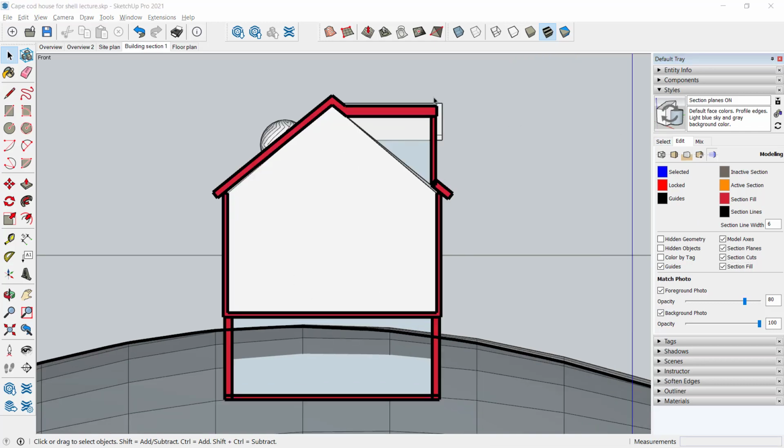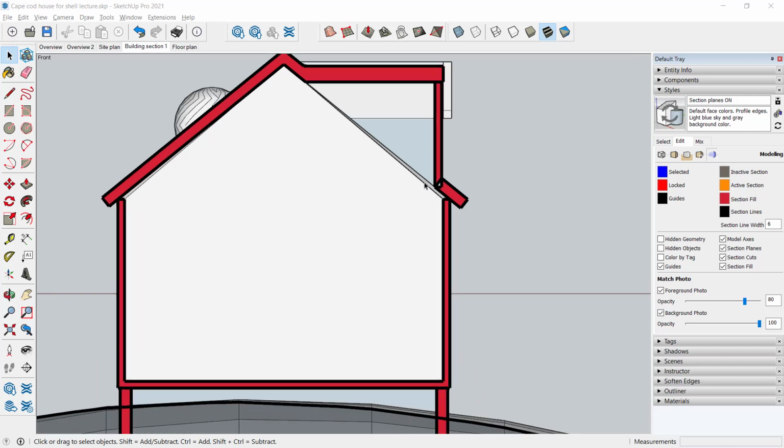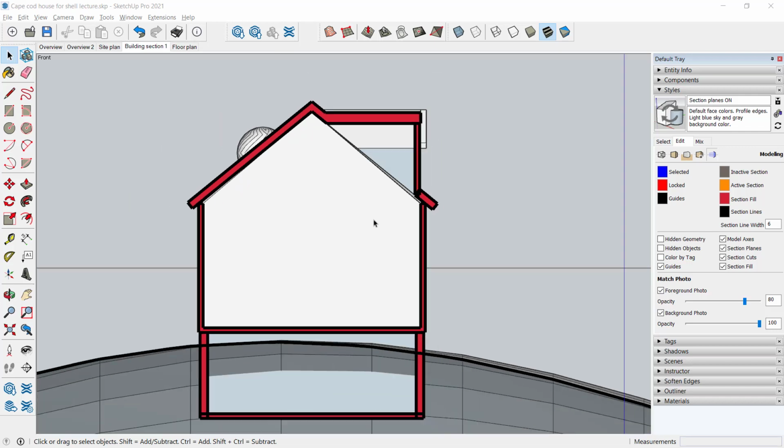And you can see here, by repairing those windows, I was able to get the section fill to look correct. It does look like there may be some other strange little odd things that may have occurred because of my multi-push-pull feature. Some of these things you might be able to fix in SketchUp by figuring out where that little wedge shape is. You could also just, unless it's absolutely critical, ignore it and fix it in Photoshop later on. We'll have to see when we go to render how that looks.